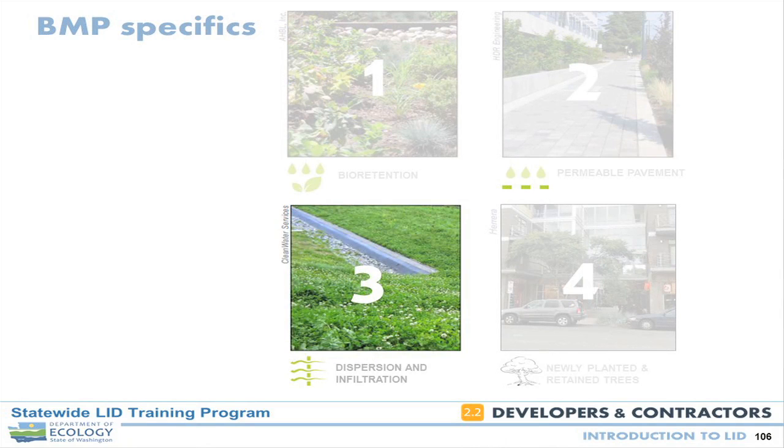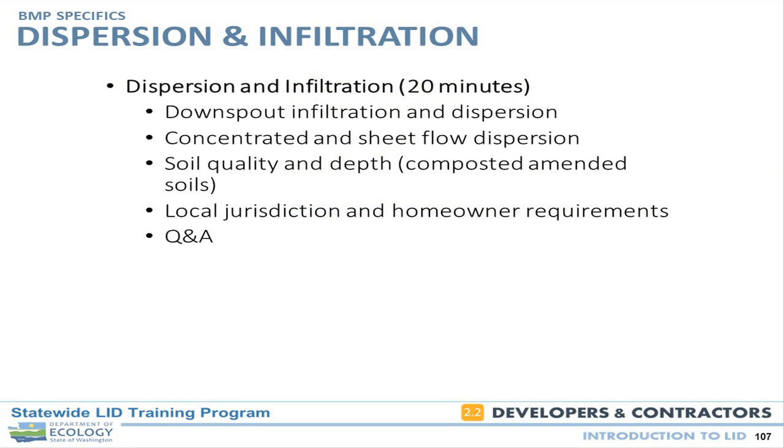Real quickly on dispersion. So this is where we are trying to take potentially piped flow and return it to sheet flow. And if our site meets the criteria for full dispersion, this can be our treatment and our flow control practice.